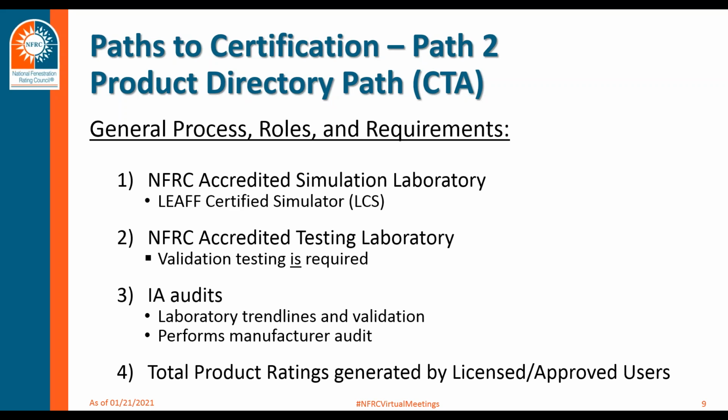The NFRC LEAF certified simulator models the products at standard NFRC sizes and configurations based on the information provided by the manufacturer. In this path, mull and composite assemblies may not be used and are rated as different product types as individual products within the project. The NFRC standard size and configuration is the mandatory rating for product comparison purposes. However, this path does provide allowance for alternate project sizing as optional.